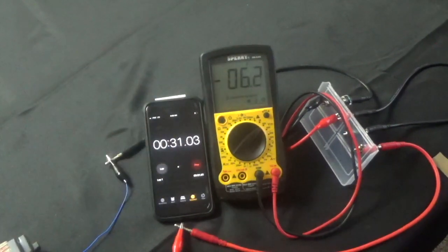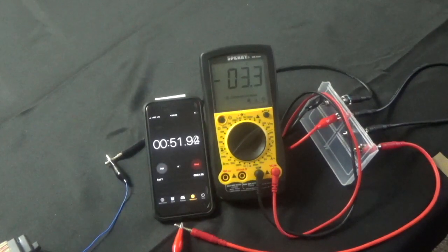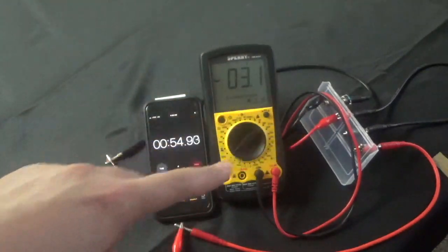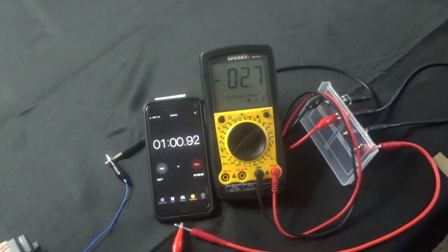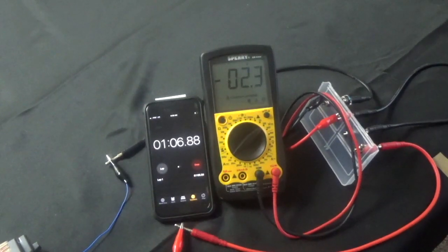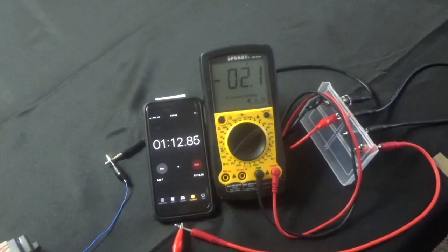The voltage is 6, yeah, and then 5, yeah, 4.9, 4.5. Okay, it is dropping right now. And why is the voltage dropping? The voltage is dropping because the capacitor is charging. And once the capacitor is fully charged, the voltage will be around 0. Let's continue. So what do we have? We have around 1 minute. That required around 1 minute.